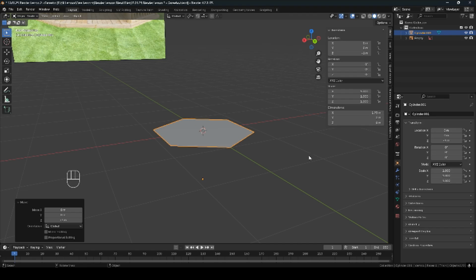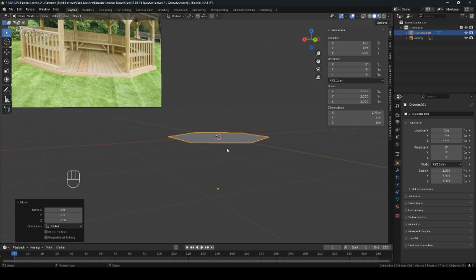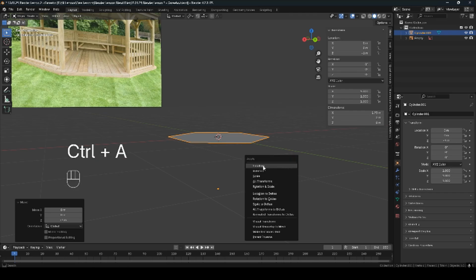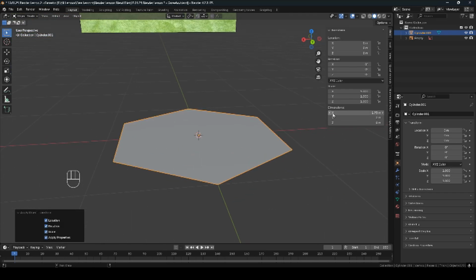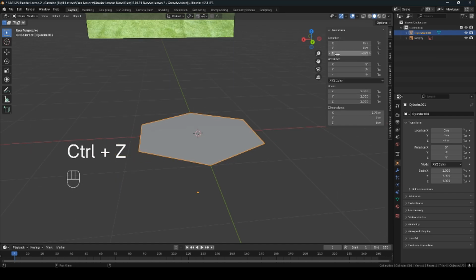What that would then do, if you look at this origin point, the little orange dot is down here in Narnia at the moment. So press Control A and then reset transforms. That will then reset the transforms, and as you can see over here, if I press Control Z, you can see, look, it's set to -1 because we did bring the whole object down. -1, but we want to now put that to 0.